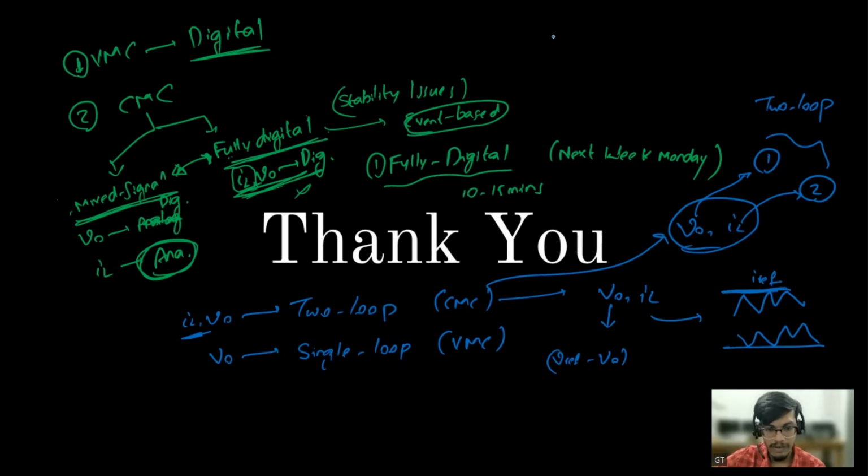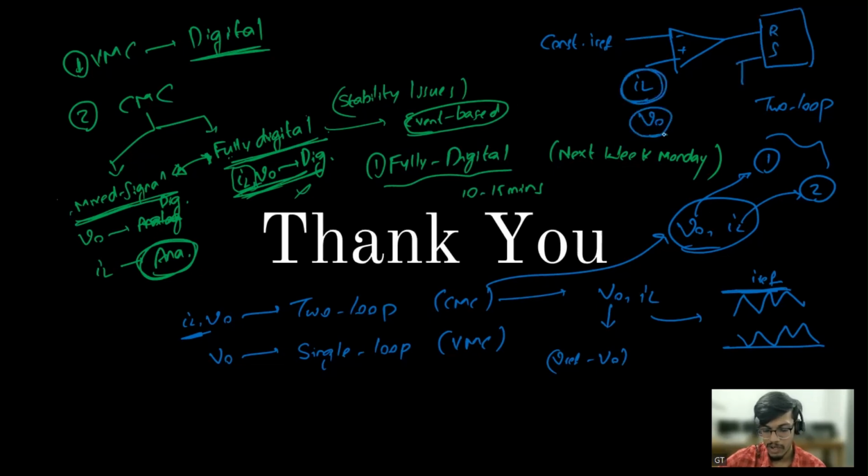So if I give constant I reference and I directly compare it with the inductor current, there is no controller here. So this is giving reset pulse, and this is giving set pulse. Now what I'm doing, I'm fixing the peak inductor current. But who is regulating the V0? No one is regulating the V0. For this peak current, whatever be the V0, the converter will be giving me that V0.